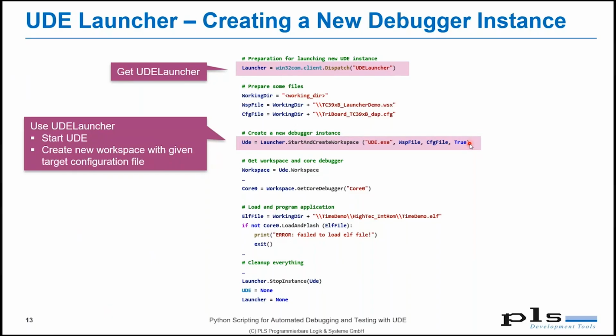Okay, then the next is that you have to load an ELF file, of course. Some application has to be loaded into the device, because if you create a new workspace, then UDE has no idea what's already flashed on the device, and so it is necessary to load and program a new ELF file here.